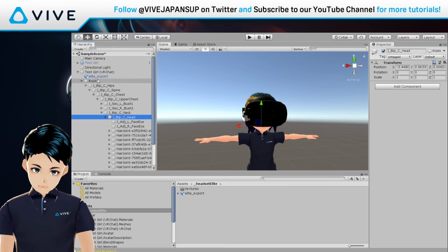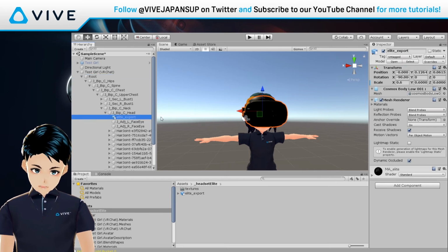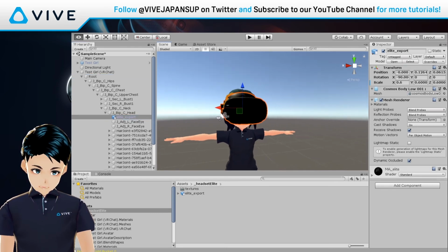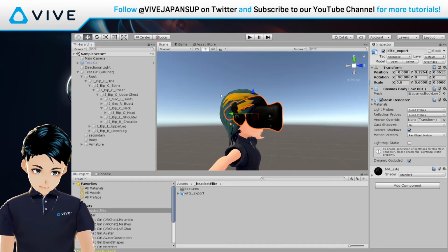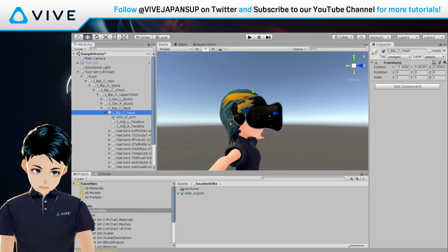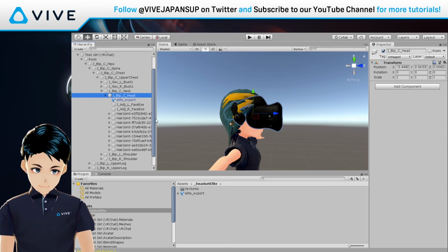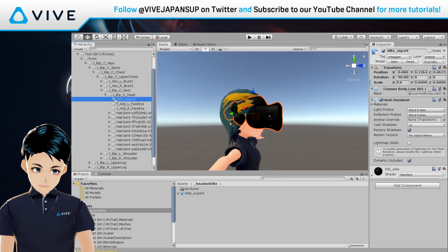So the head bone is here under the root. I'm going to move this here. Okay, I hope that makes sense for everybody. So now that this item is here, when you move your character, that whole bone's going to be working. The head bone. That HMD is going to be stuck to your face and moving in the right direction. What's also important is that this object is in the high level. If you put it down here for some reason, it doesn't work with me. It kind of impacts which bones it's working on. So just keep it up here.